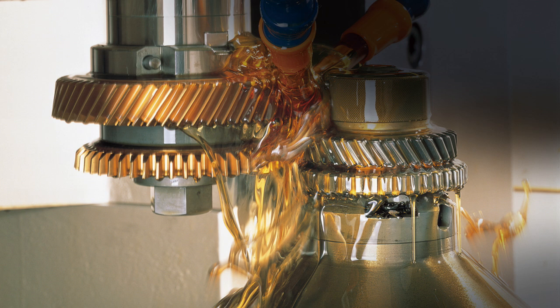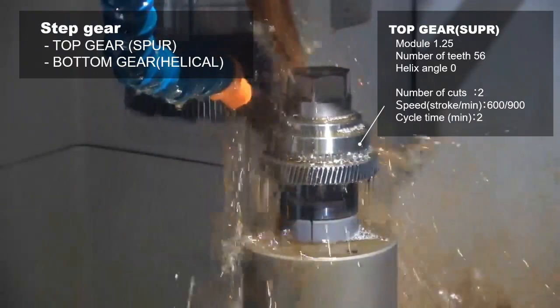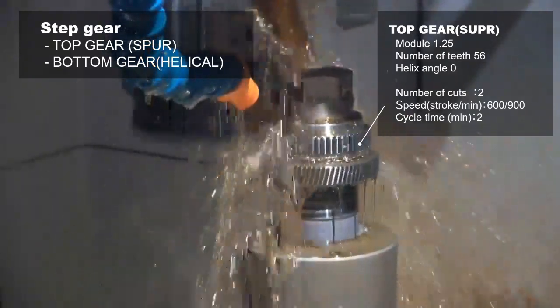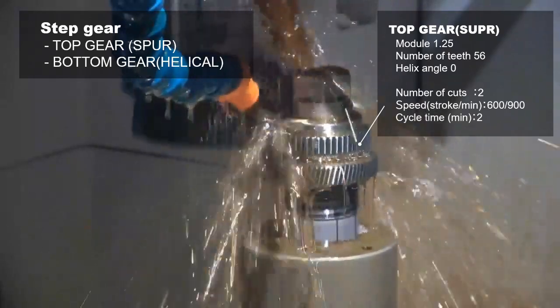Special considerations for shoulder gears. When working with shoulder gears, it's critical to ensure a clearance of 1 mm, 0.04 inches, or more between the edge of the cutter blade on the relieving side and the shoulder end face. This prevents interference and ensures proper gear function.